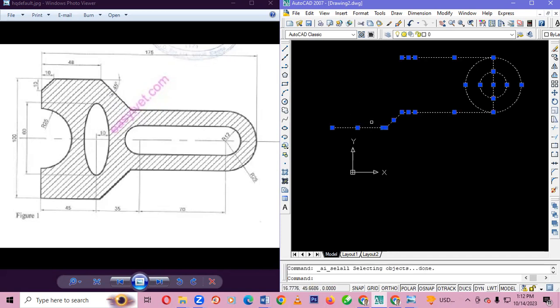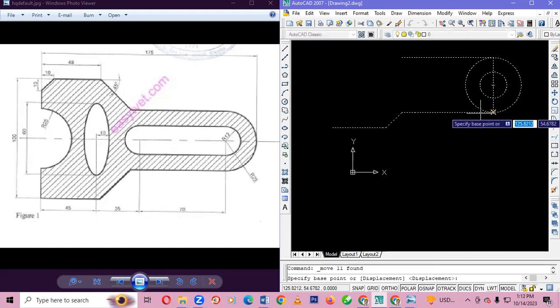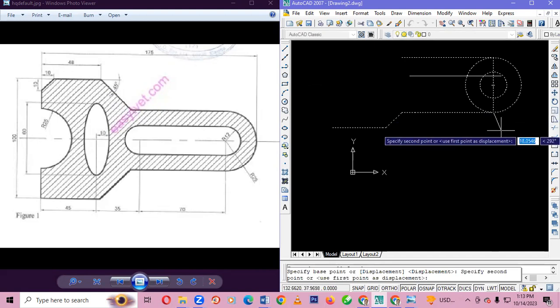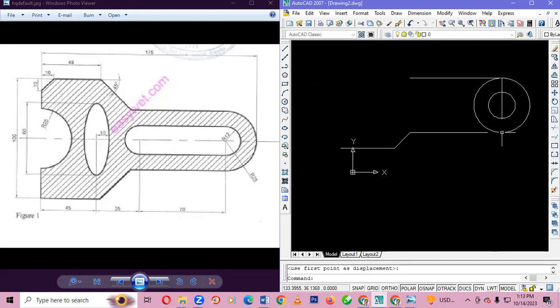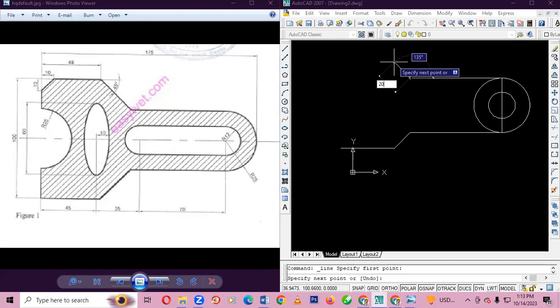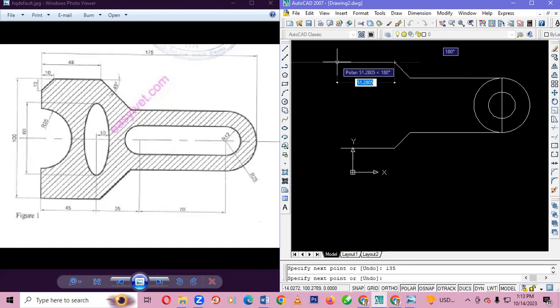So what I'll do, I'll just first move my shape below so that we can draw going upward. So once I move it below here, I'll be able to come up with a shape that can communicate. So in this case, I'll click on the line. Then I click here. Since we said 20, now also at the top here, it's 20, like this. So when you draw 20, you press tab, you apply 135, then you press enter. Then you can start going to this particular given side.